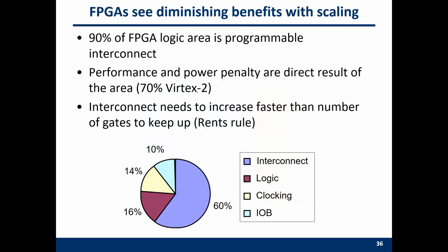And on the FPGA board, because of the traditional 2D process technology, 60% of the area is occupied by the interconnections. So the wire delay, the interconnection, dominates the performance of your FPGA board design. We only use 16% for the CLB, for the real logic.